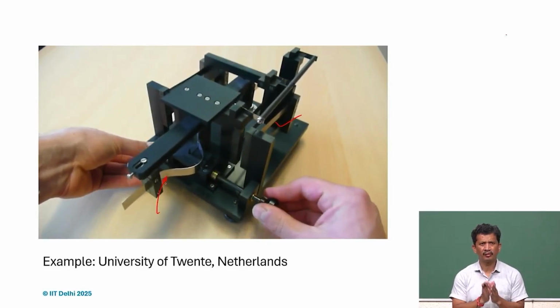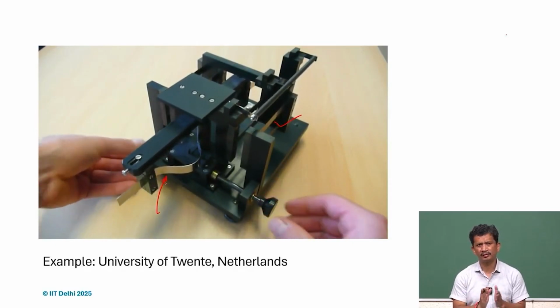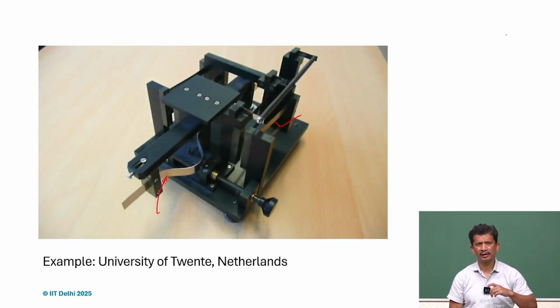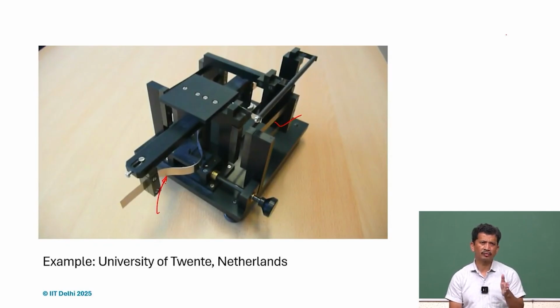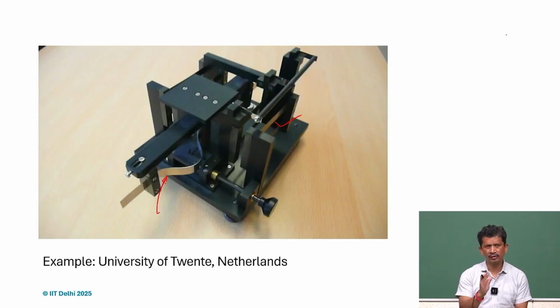But as you were tuning it, and the positive and the negative stiffness are tuned, what you realize is that the free vibration mode, the fundamental mode, is really small. If we compare with the square root of K divided by M, the K is near 0, it means that omega can be very small.